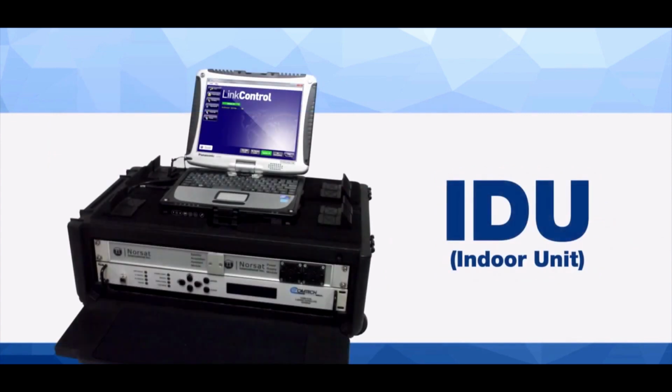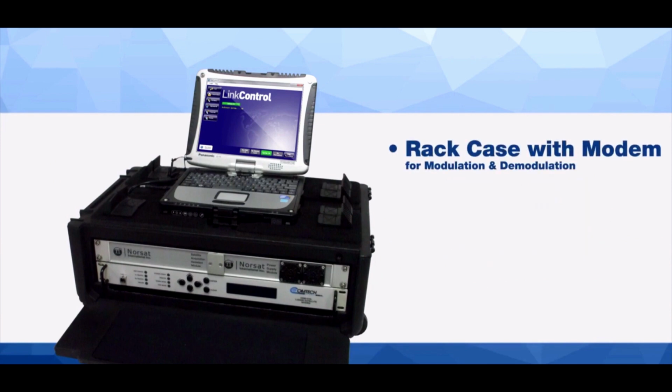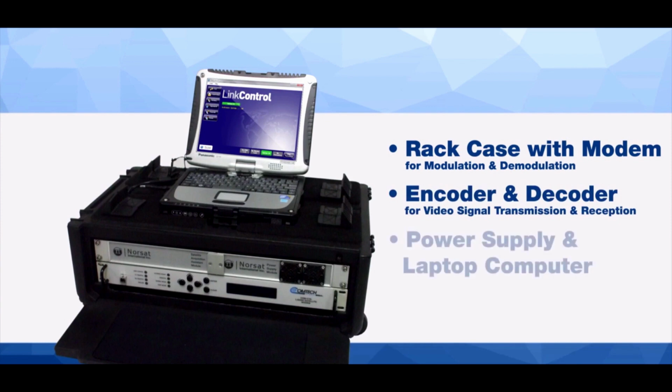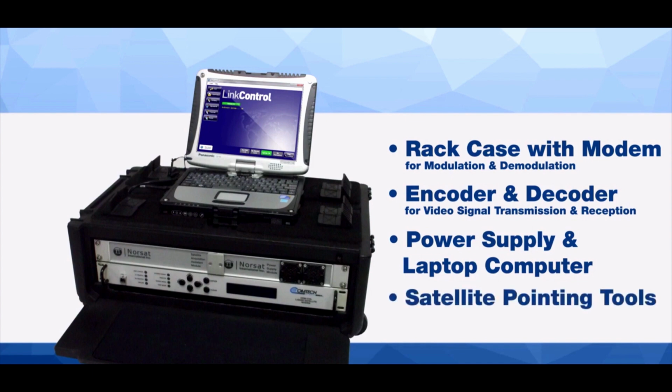The IDU, or indoor unit, processes the receive and transmit signals from the satellite. Typically, the IDU will consist of a rack case with a modem for modulation and demodulation of a satellite signal. It may also contain an encoder and decoder for video signal transmission and reception. A power supply and laptop computer can control the terminal, and satellite pointing tools may also be integrated into the